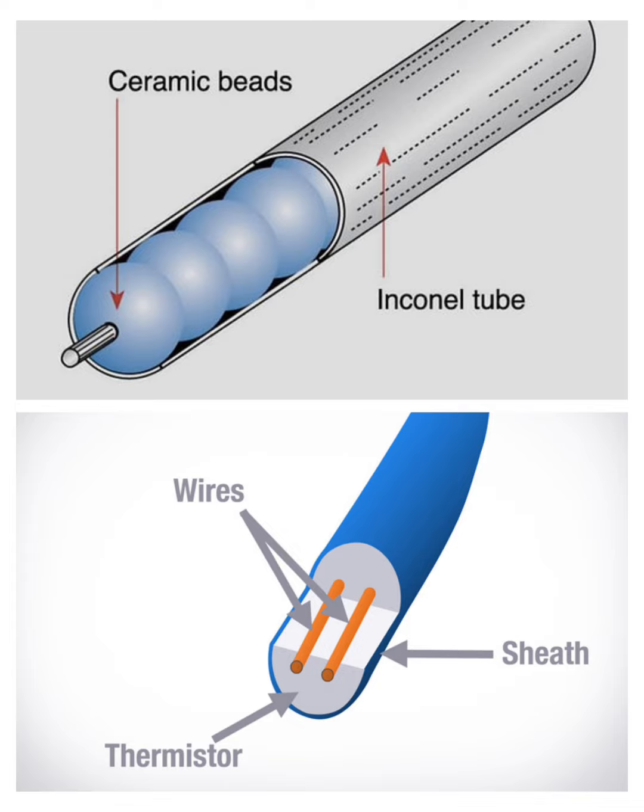Describe the operation of a Kidde continuous loop fire detection system. Two wires are embedded in a special ceramic core. One wire is internal ground, the other wire is a hot lead. The ceramic core material heats up, its resistance drops, connecting the internal wires, completing a circuit, energizing a light.